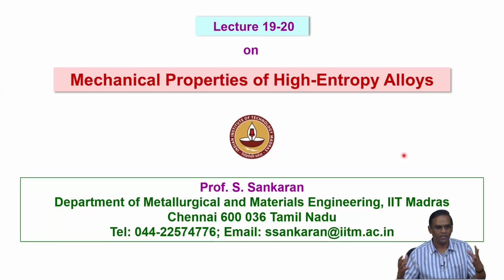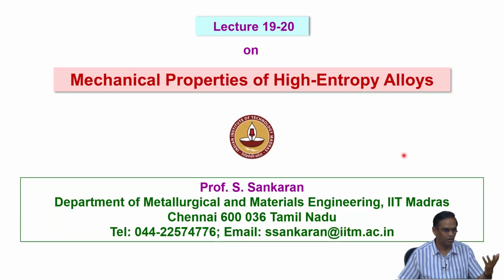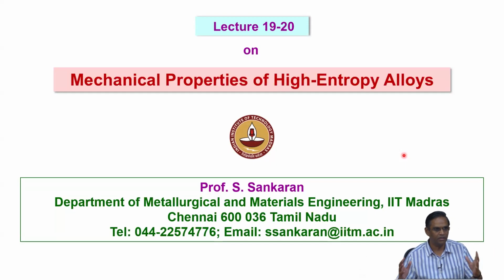If the material exhibits very high stacking fault energy, the dislocation movement will be easily permissible, or the three-dimensional motion of the dislocation structure is easily possible. That means we talk about cross slip, multiple cross slip, and so on, which is easily facilitated.